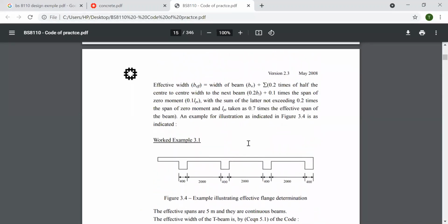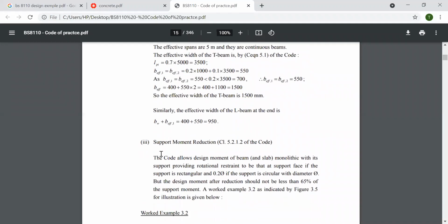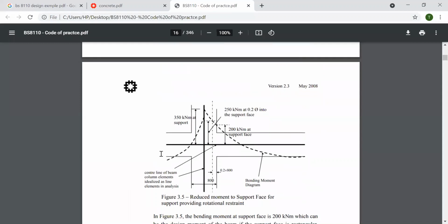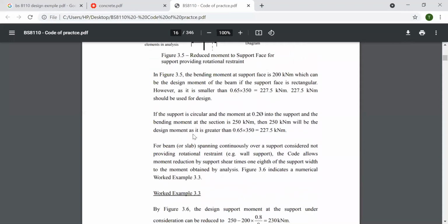This is the work example number 1, all right? This is the beam, etc. In our case, usually we find the beam section only. This is the flange T-type section where the effective beam width is also considered in the section. Support moment reactions and the curtailments, I said to you, how do you find them through the bending moment envelopes?